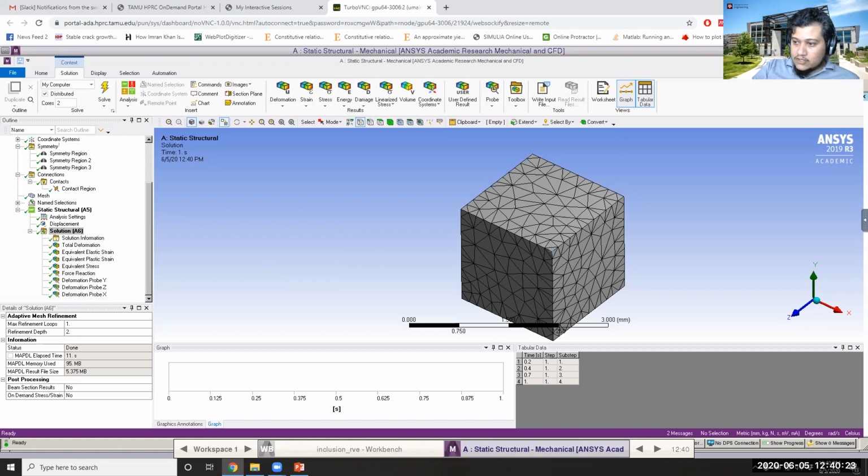Okay, would one of these options allow for the two bodies to separate and come into contact repeatedly? The frictionless contact will allow it. Okay, but make sure that this going away and coming together thing doesn't happen at a very high frequency, because if it is happening at a very high frequency, your problem is no more a quasi-static one, rather it will become a problem of transient analysis.